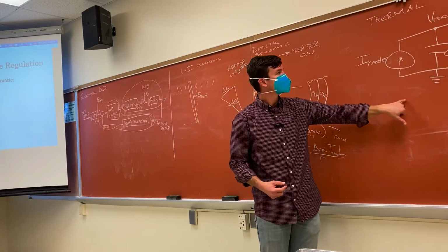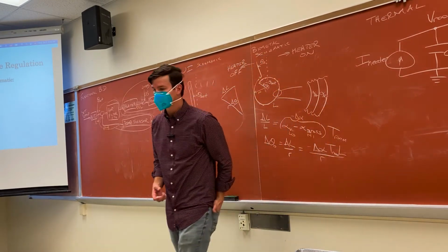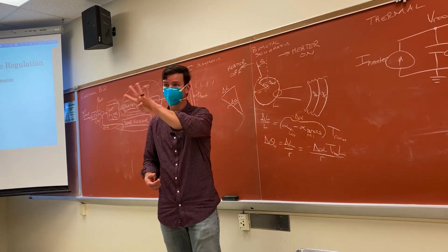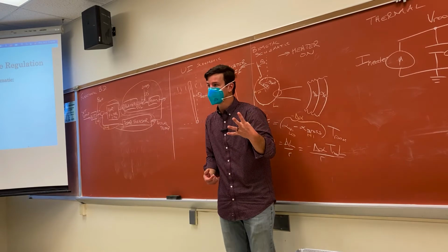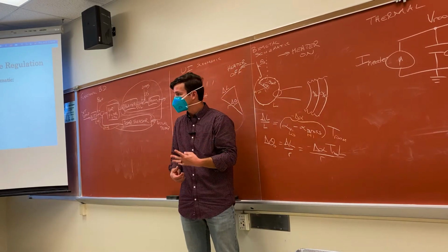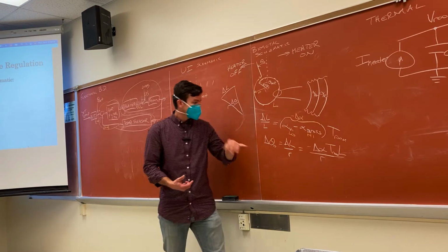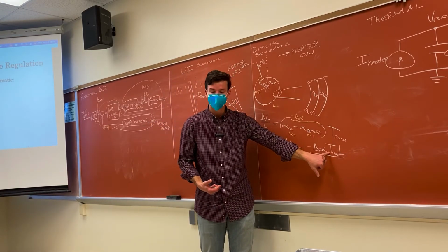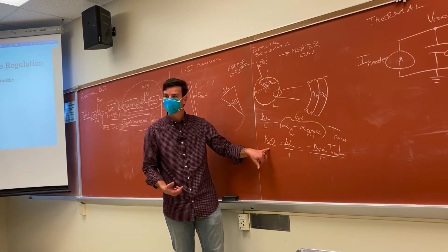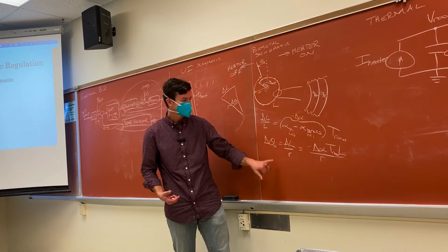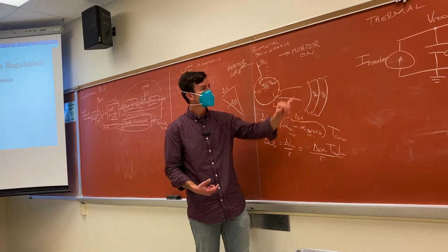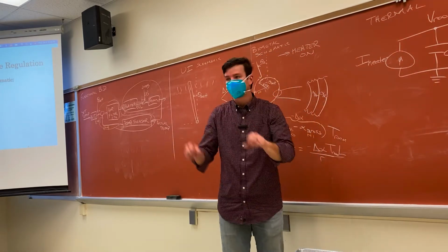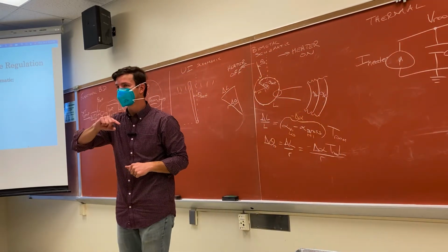So let's talk about this circuit. What I would like is a transfer function, because in my Laplace, I'm looking into the future. My step 4 is called a Laplace block diagram, and inside of that Laplace block diagram, we're going to have a bunch of transfer functions. This is a transfer function from room temperature to angle. There are no S's here because it's an amplifier. Here, we're going to have some dynamics because we've got the capacitor. But there are 2 inputs to this circuit. Yeah, there are 2 independent sources.